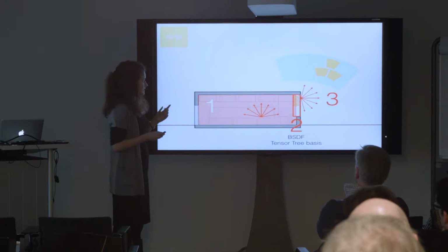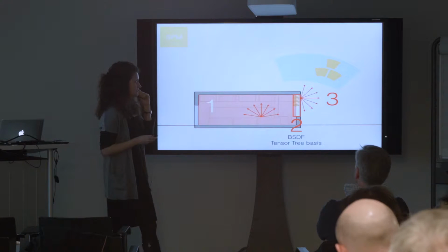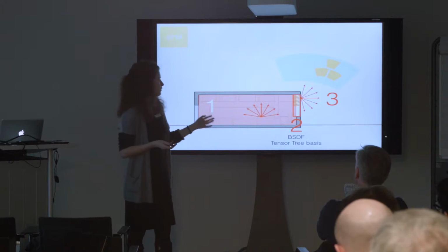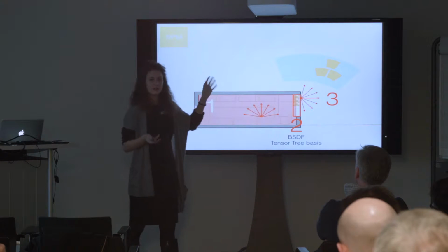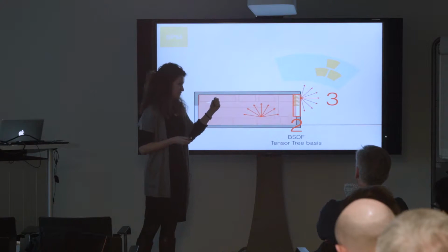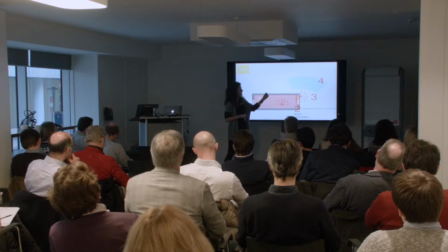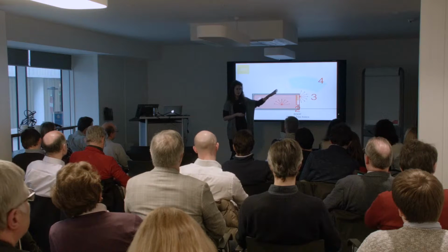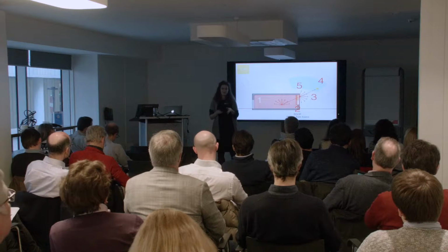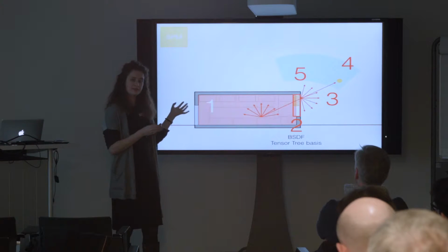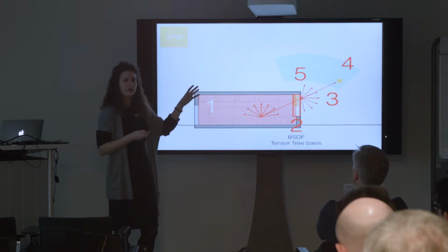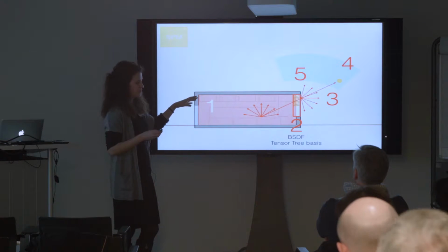And after the three-phase method, the five-phase method is a refinement of that, and it starts actually from the three-phase method output. So we are in the situation we were before. We got our illuminance value and all the rest from the three-phase method simulation, but now we add two steps. At first, we take out the direct sunlight, as we calculated it with the three-phase method, and then we re-add it, but using a more refined strategy, so that the diffuse light remains the same as the three-phase, but the direct component, which is the more delicate one, is now more accurate and especially more realistic in images.